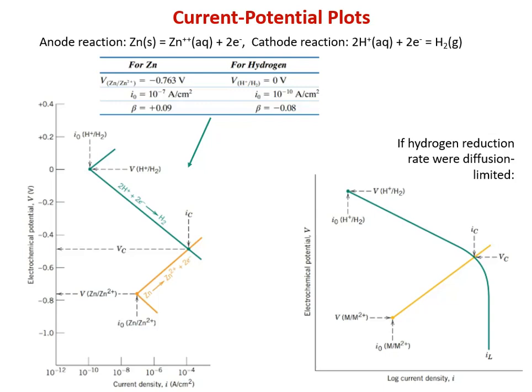That current is constant. And effectively, the potential goes to infinity, because under limiting current, changing the potential does not change the current. It is now independent of potential and is merely awaiting diffusion. So that really changes the relationship when you look at what's happening with the zinc, because now you're going to intersect those two corrosion half-cell curves, current potential relationships, at a different point, usually resulting in a dramatic reduction in the overall corrosion current.